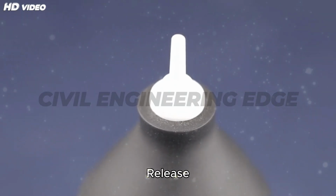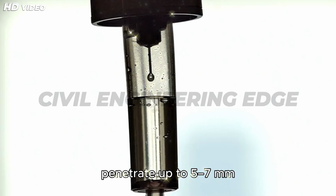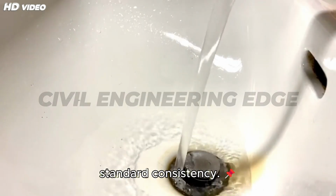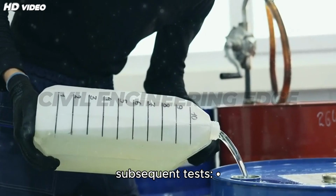5. Release plunger, 10 mm diameter, 50 mm length. The plunger should penetrate up to 5 to 7 mm from the bottom. Adjust water percent and repeat till you get standard consistency. The water percentage at this point is known as P, used in subsequent tests.